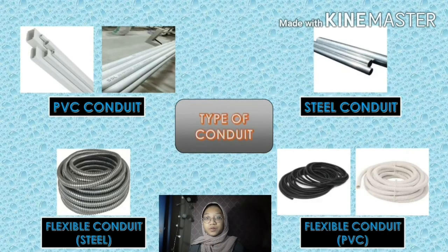Types of conduit. Electrical conduit is a piping system that protects wires and cables from impact, moisture, and vapor. It is a path for either power or communication. It means low voltage electric wiring. It is usually tubular and made of metal, such as galvanized steel, stainless steel, aluminium, or non-metallic materials like plastic. And it is either rigid or flexible.